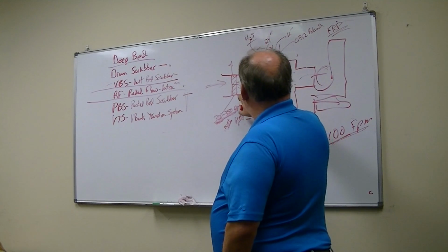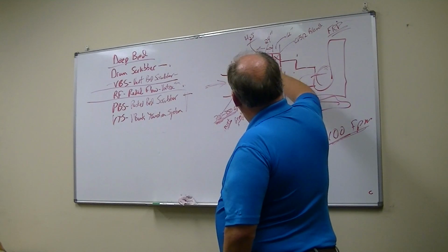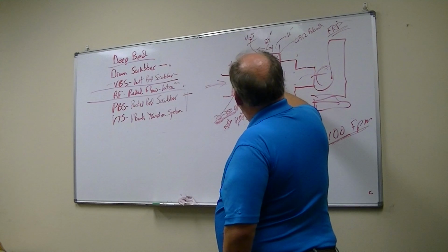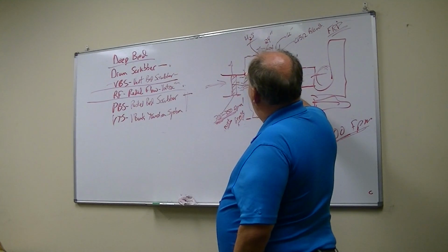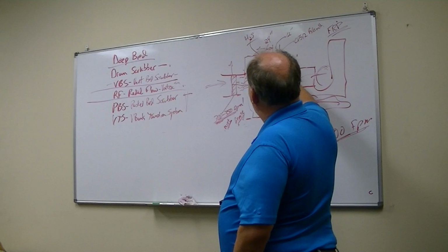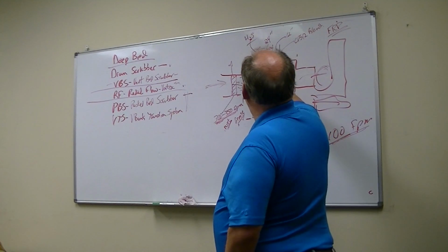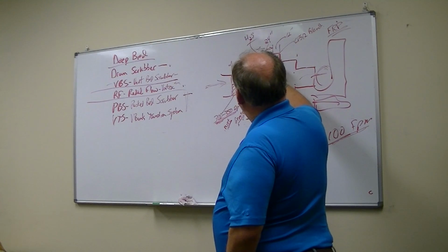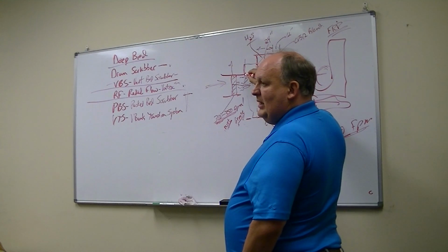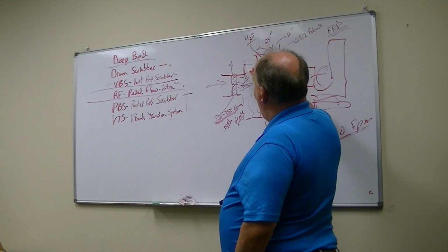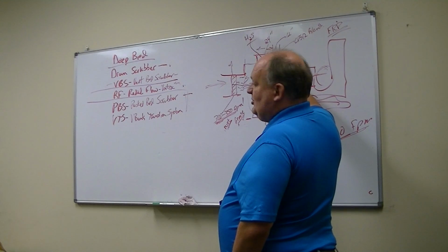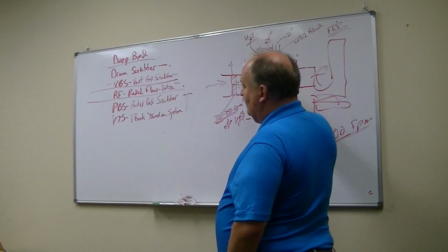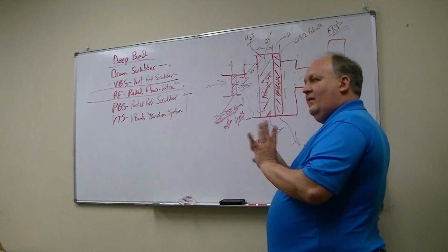Okay. So the typical rule of thumb is that you want the maximum point here, hold on just a second, I've got to fix this, to the maximum, so the highest point of the media, of the mist and grease filter area, and the highest point to the carbon bed to be about 45 degrees, okay? Again, that's rule of thumb-ish.